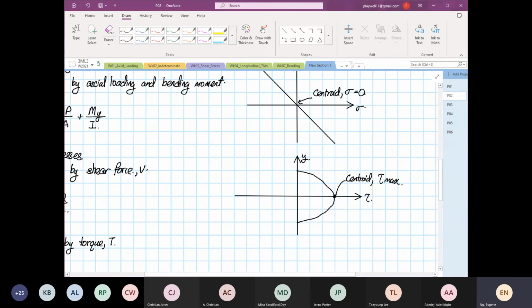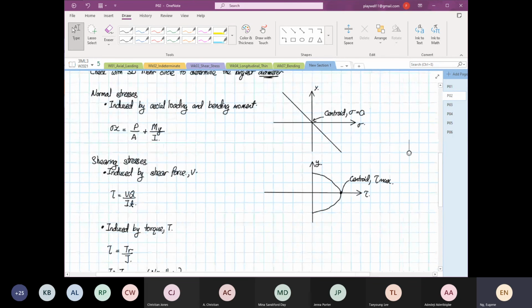You say, oh, right? And when I was a young engineer, I was not taught like this. This is when I discovered, maybe when I was doing my PhD. I thought, okay, if the normal stress is higher, just use the normal stress. My shear stress, I don't know what it is, don't know how to incorporate them. Okay, I just put a safety factor of 2.0. We're good to go. Okay, we have to be careful with that. Maybe sometimes your factor of safety of 2 is not enough. Okay, we have to be really cautious in situation like this.